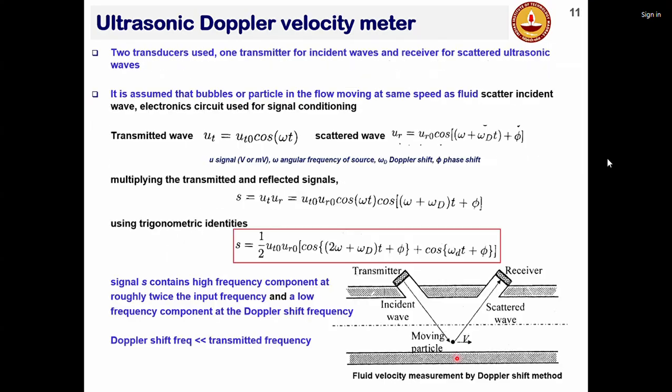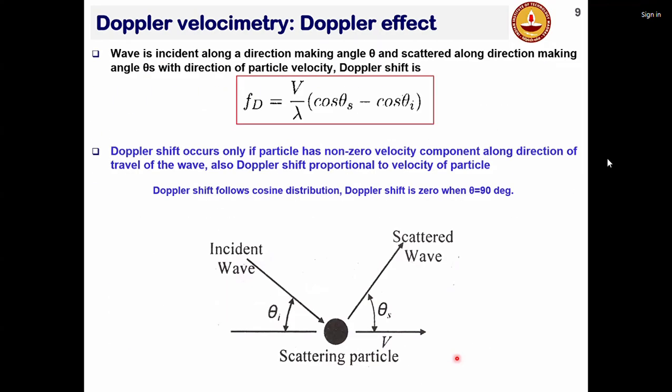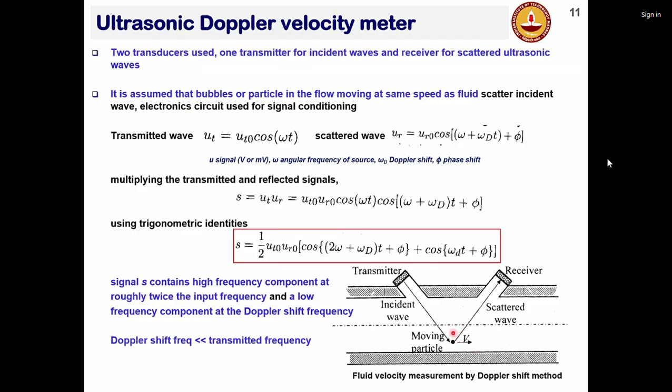The output gives you the Doppler shift frequency. And your control system also has this algorithm, because in appropriate design you know the angle of incidence. In this particular case, this is the flow velocity. So you know theta s here, theta incident here, and theta scattered here. These angles are known by design because of the placement of the receiver and your point of interrogation.